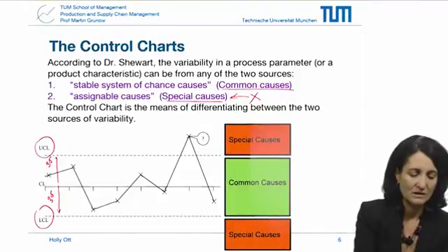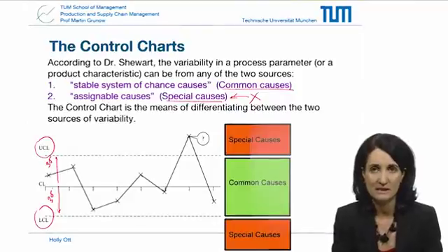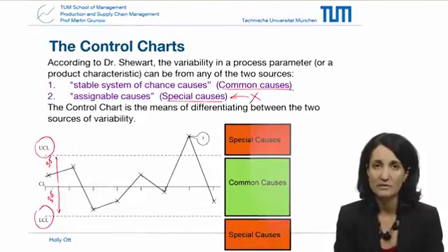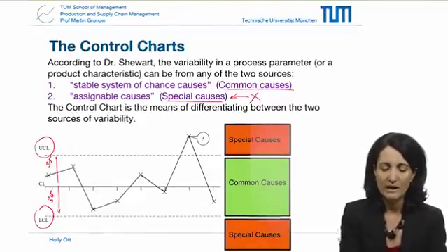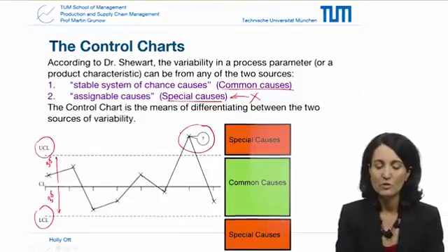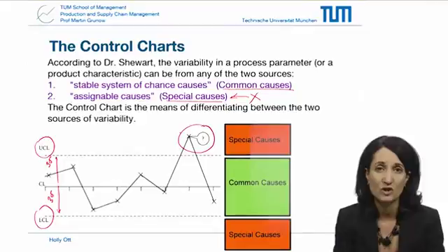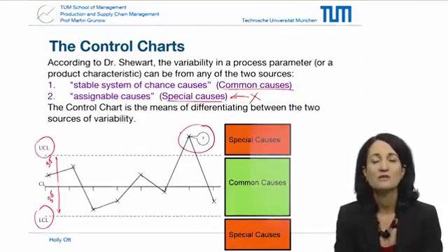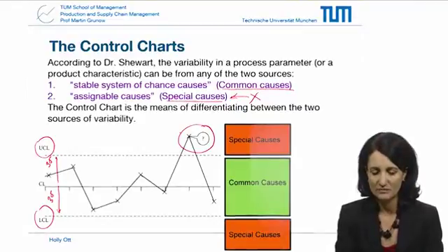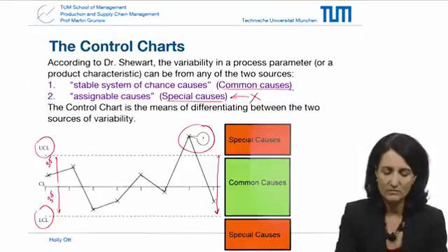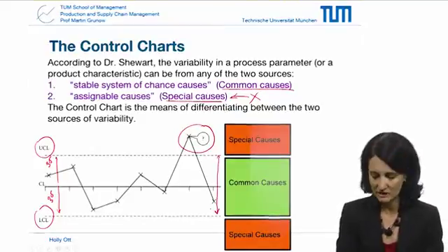Again, the sigma here is for the sample statistic, for example, the X bar. And then we would plot data from our samples, generally with time, and if something fell out of the control limits, we understood that we had a special cause. We understood that we had a variability that was due to something that is unexpected. In between these limits, we would see variation due to common cause variability.